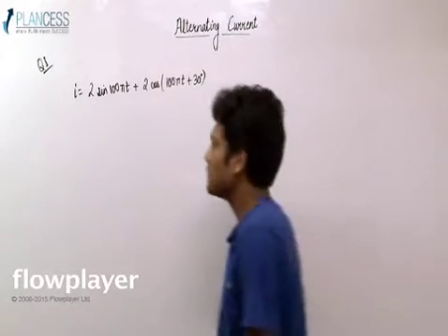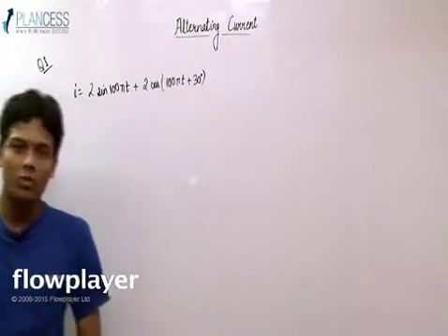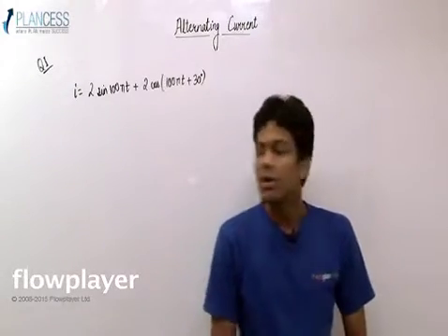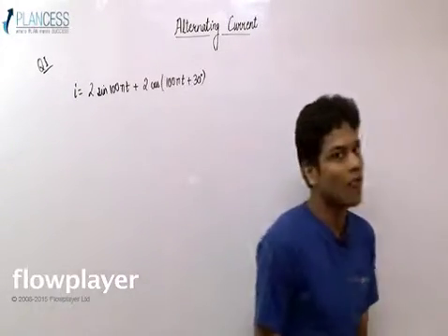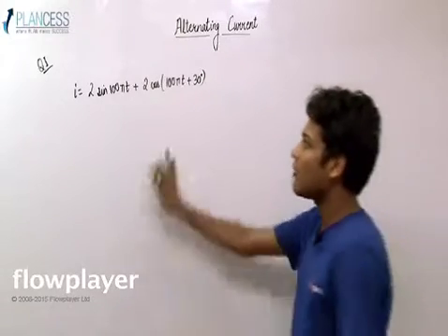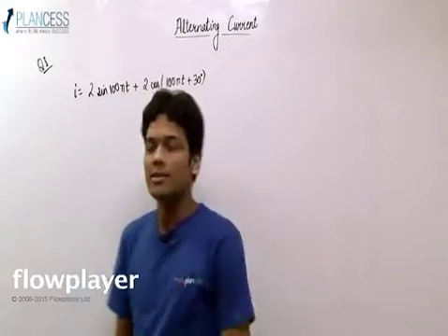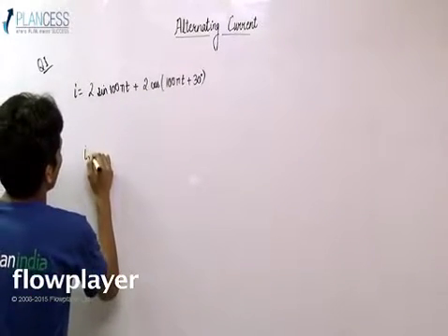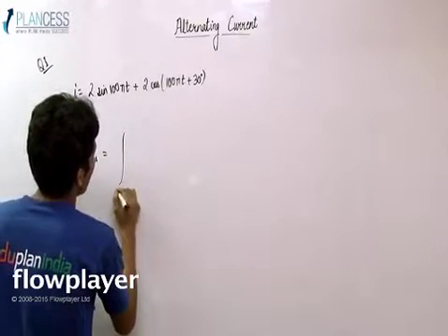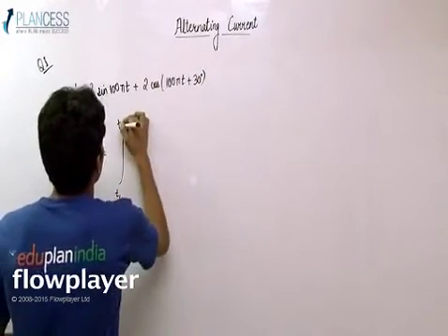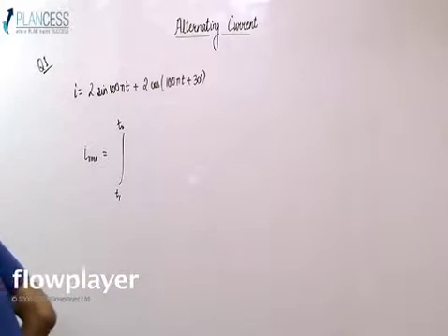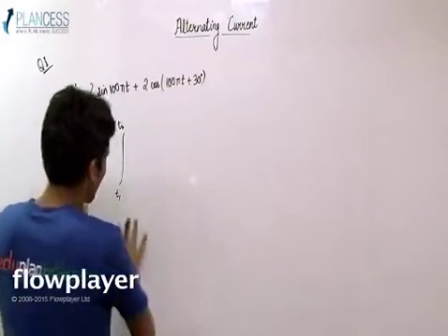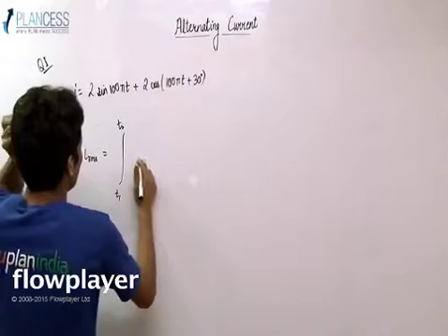You must understand this properly. What is effective value of current? Effective value of current is basically the RMS value of the current. So this is the function of I given to you. You have to calculate the RMS value of this current. Now, as we studied in the basic module, we have a formula for calculating the RMS. I can write down I RMS, that is root mean square, and you have to calculate it for a particular time, that is for one time interval.